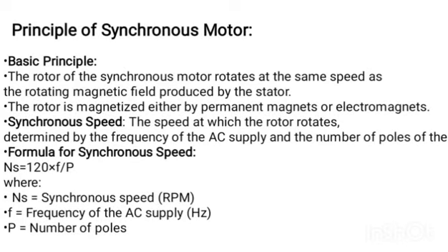Next, I will talk about the principle of synchronous motor. The basic principle of this motor: the rotor of the synchronous motor rotates at the same speed as the rotating magnetic field produced by the stator. The rotor is magnetized either by permanent magnets or electromagnets. So this is the principle of synchronous motor.